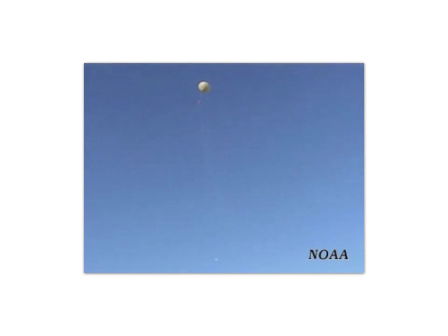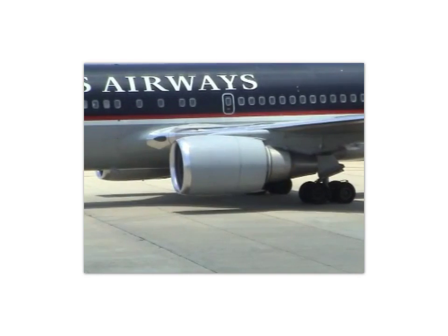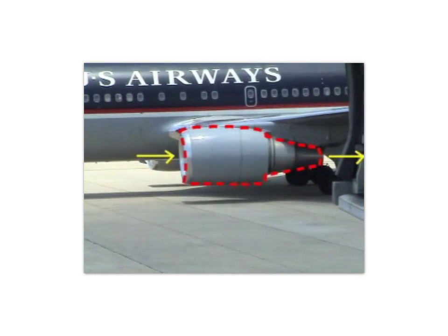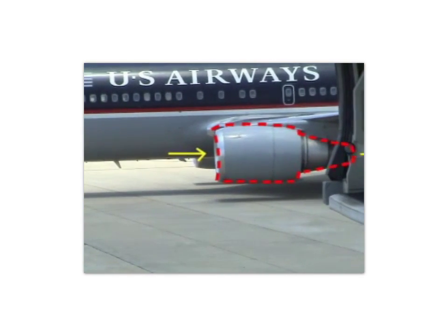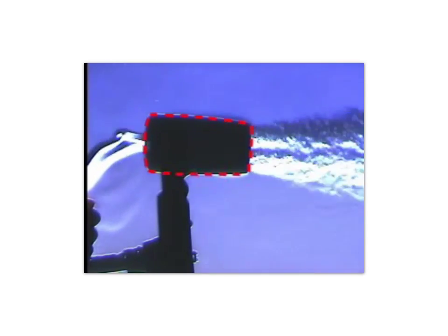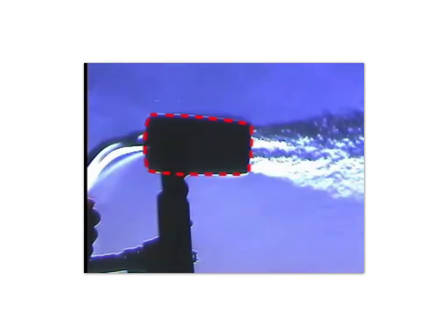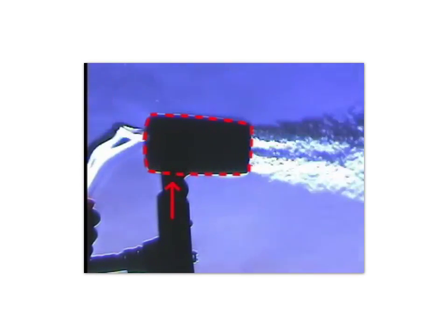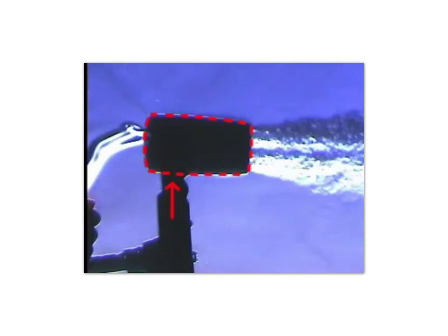This reference frame is inferior to the Eulerian approach, however, in treating the airflow through a jet engine. In this case, a control volume is fixed to the jet engine with air flowing through it. Likewise, an appropriate Eulerian control volume for this hair dryer is fixed to the dryer itself rather than to the air passing through it. In this simple example, the control volume has one inlet and one outlet, and its lateral sides are impermeable to the air. Electrical energy enters the control volume, however, in order to heat the air and drive the blower that moves it.